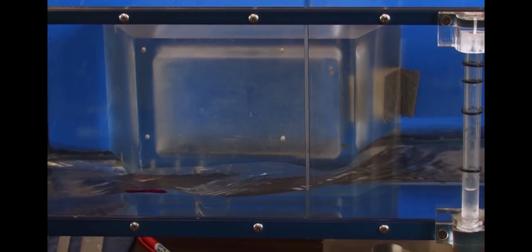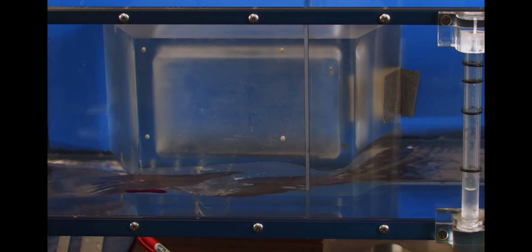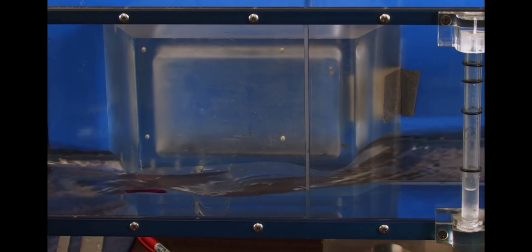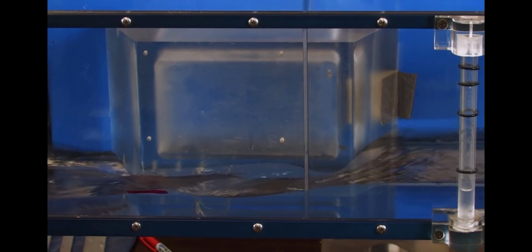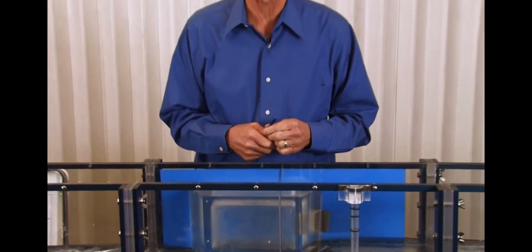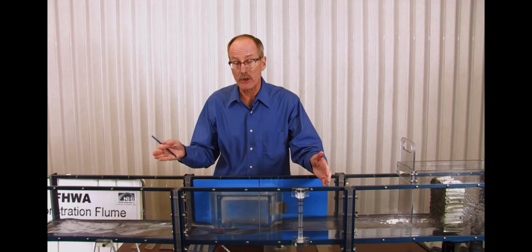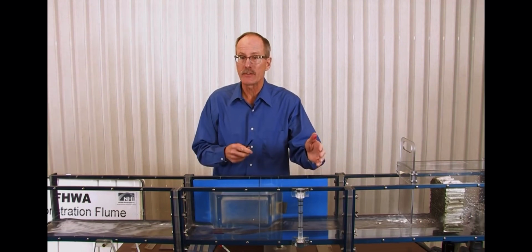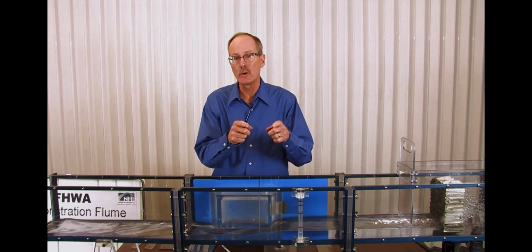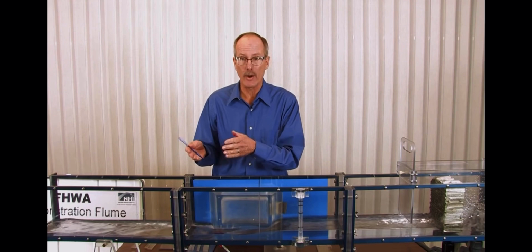This leads to another equation that we use quite often in open channel flow. It's called the continuity equation. The continuity equation is really just a restatement of something we all learned in physics, the conservation of mass. So if we have continuity in a hydraulic sense, then the discharge is constant, and because of that, the continuity equation says that the discharge is equal to the velocity v times the area, the cross-sectional flow area.